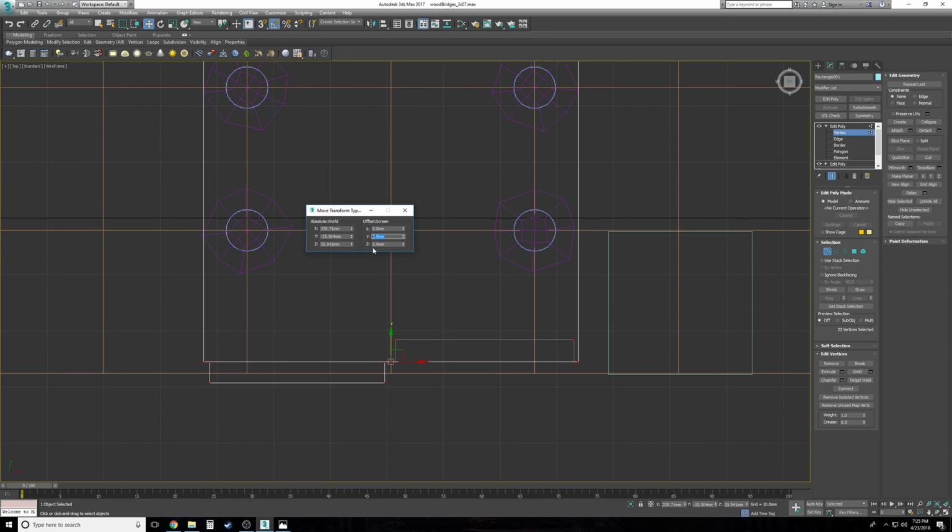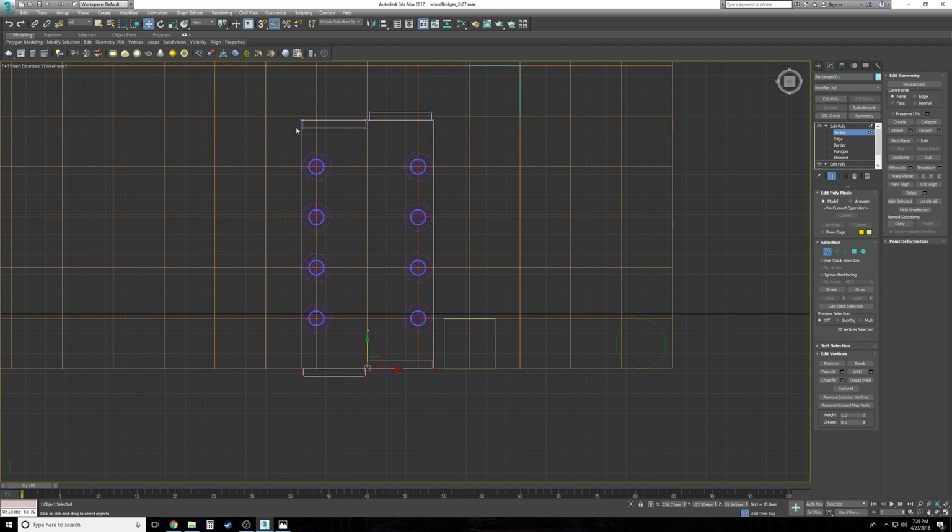So what we can do, knowing the distance between that, is go over to this offset screen, and you basically tell it a distance of coordinates. Right now we want to go downward in our screen, negative 2 millimeters. And that's what it does. We already know it's going to be universal on both sides because we've done the math. So it's going to be 2 millimeters vertical. So this is going to be 2 millimeters positive on the Y. And you're lined up.